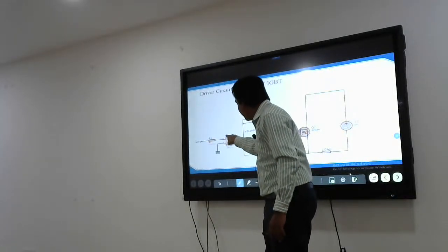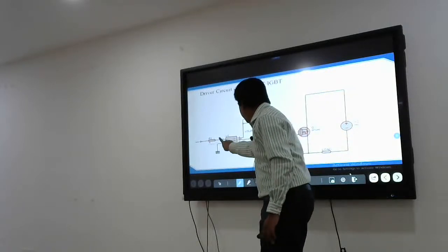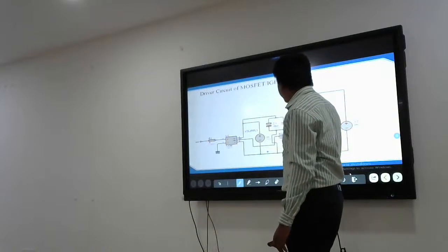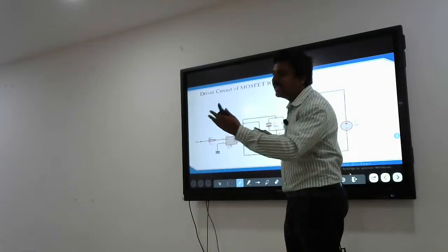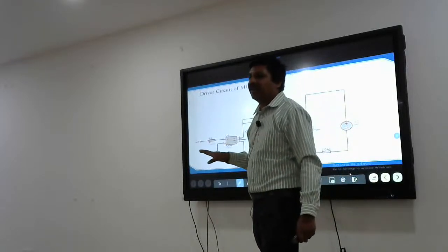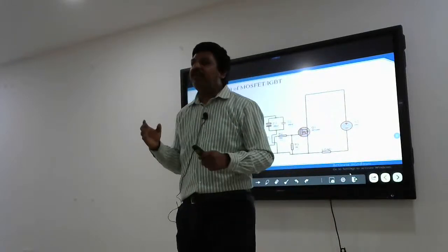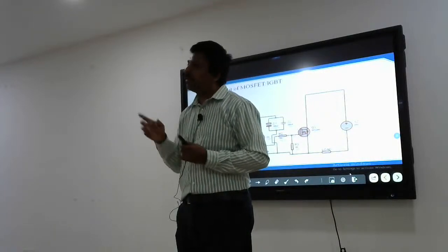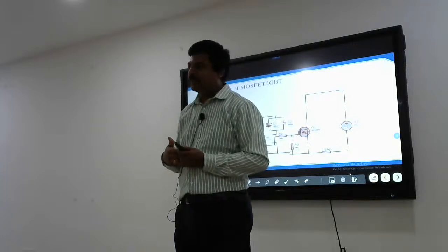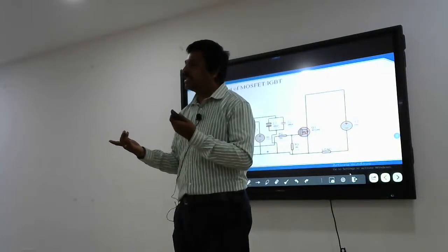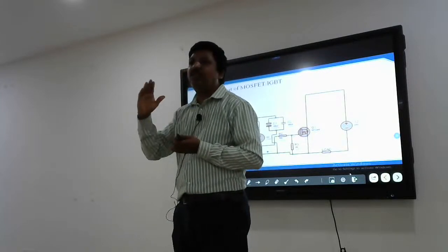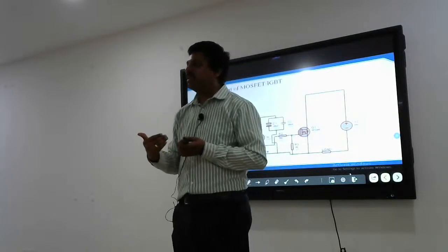Only thing is, there is no connection between the control circuit and the electrical circuit. So you get 12, 0, 12, 0, and this is given to the MOSFET. When 12 is given the switch is on, and when 0 is given the switch is off. But this is about MOSFET. When it comes to IGBT, you should give different voltage levels. It is not always 12, 0. For MOSFET, 12, 0 is fine, but for IGBT, 15 and -5. For IGBTs like Semikron stacks, they operate at 15 volts for turning on and minus 5 volts for turning off.